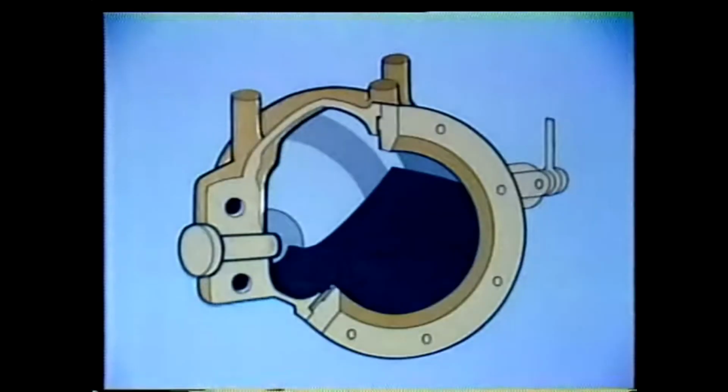Well, cryogenic valves are usually constructed from materials such as bronze and austenitic stainless steel. These materials do not generally become brittle. Carbon steel found in many regular valves is not used for cryogenic valves because at very low temperatures it becomes as brittle as glass.